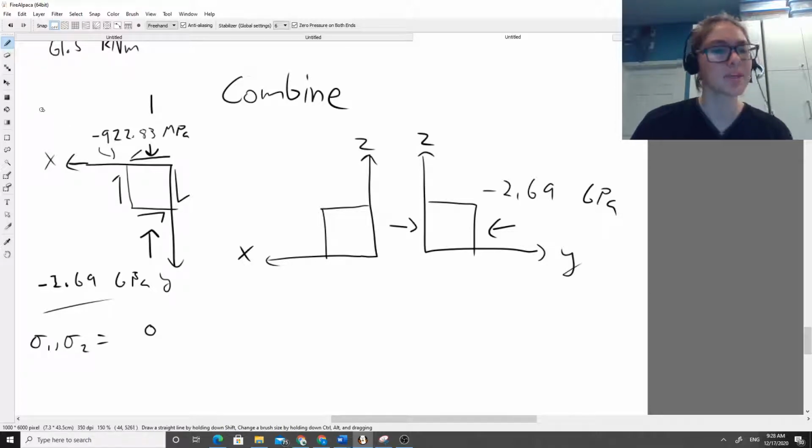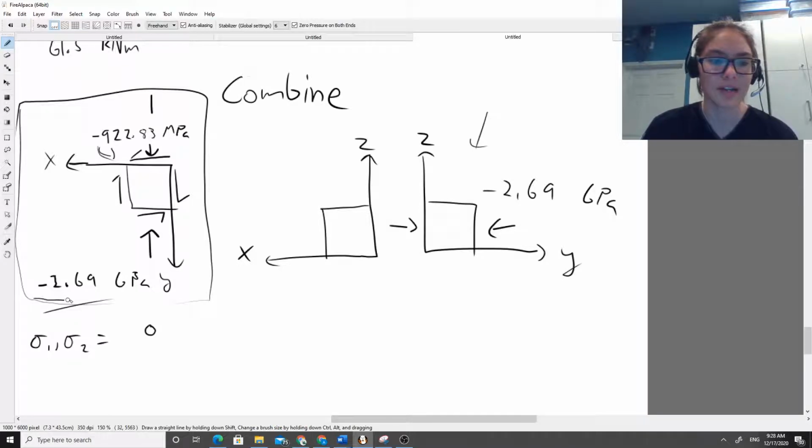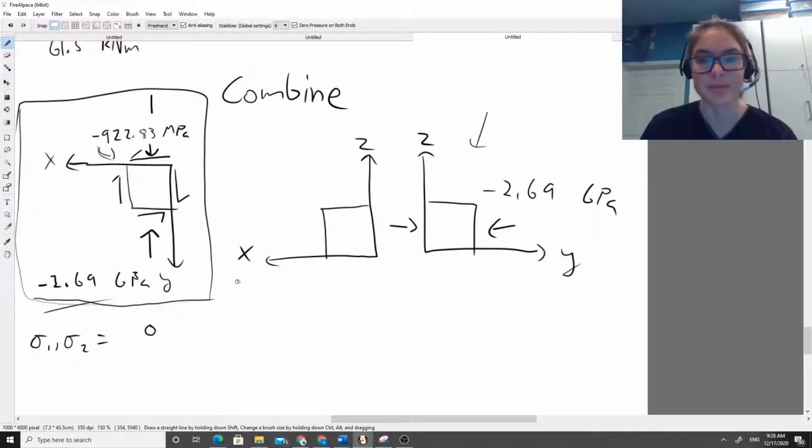That's obviously going to be XY here because this has a negative shear stress as well as the same normal stress that ZY does. So we're just going to be focusing on this stress block. It has the most stresses on it, which is fairly obvious. If it wasn't obvious, you could just solve for each stress block and see which one gives you the largest numbers.